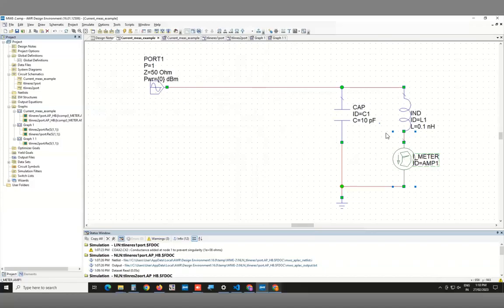So whatever energy you put in will not leak out so easily. Consequently, it will also not leak in as well, but that's okay. Just control the coupling between the two. It's equivalent to having changed the impedance of this 50 ohm to some higher value and put that other capacitance in parallel with this particular capacitance.